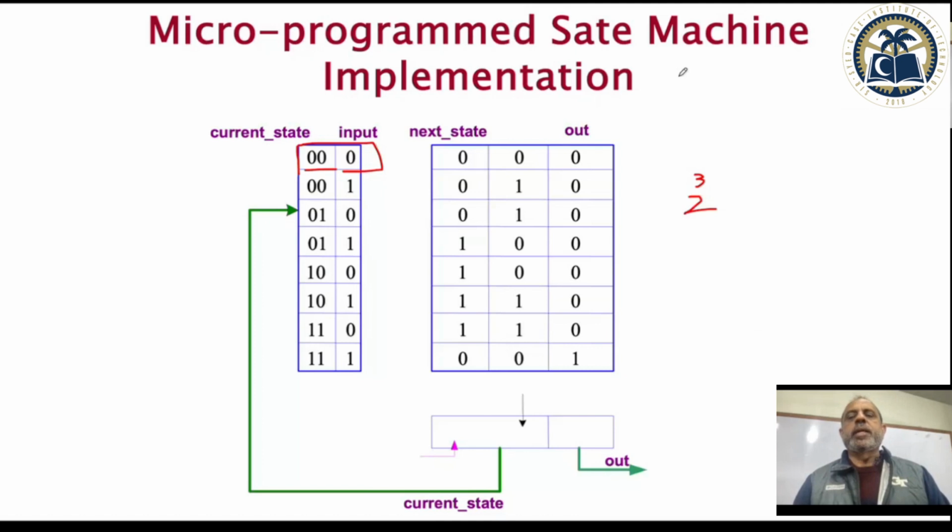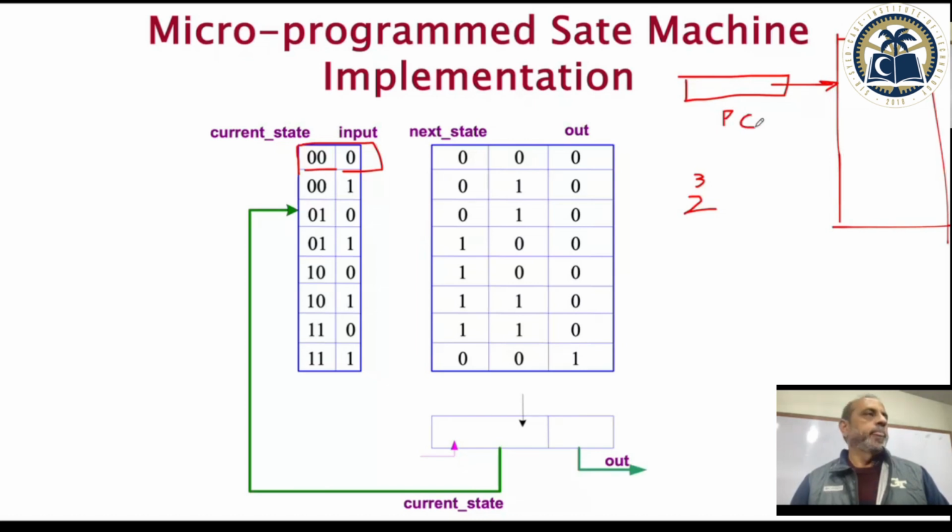That's why the program counter register size will dictate how big a program memory you can address. So the size of the program will depend upon the size of your program counter register. If it is 16-bit, your program memory cannot be bigger than 2 raised to the power 16. Okay, 2 raised to the power 16 is the size. You cannot go beyond that, and that's how you figure out how big a program memory you can have.